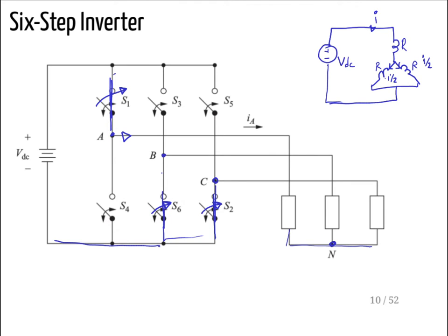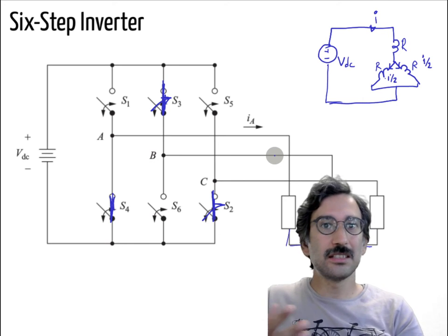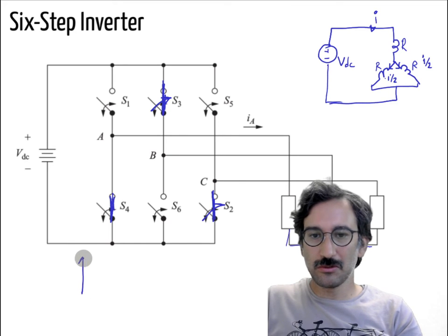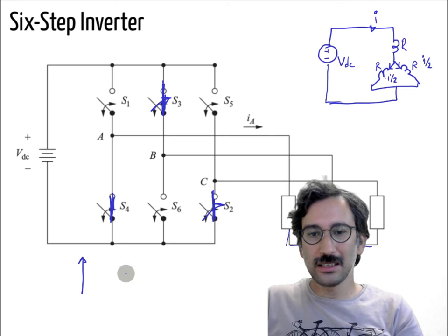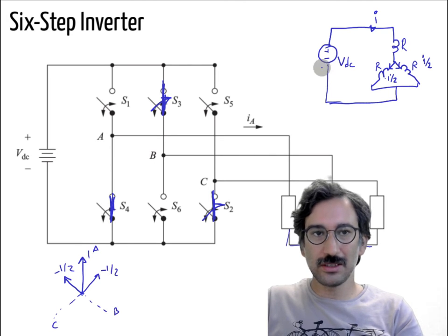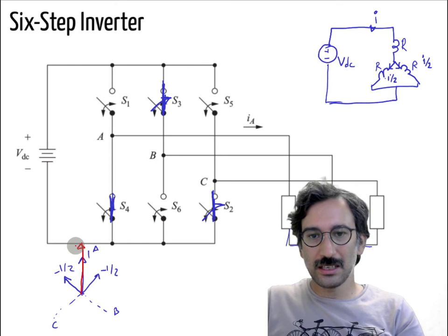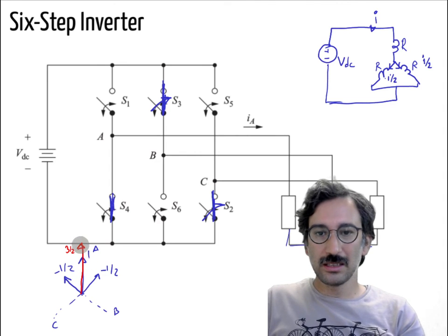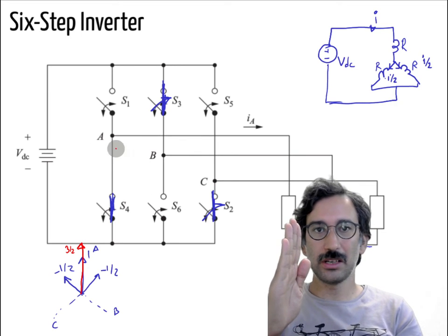We will talk about the sequence as well, but let's say you are turning on that one, for example, then B phase is on, and then the other legs are closed for B and A. If you think about the phasors and MMFs, the motor DQ axis, as you have seen, in this one phase A current is I, and the other currents for phase B and C are minus I over 2 and minus I over 2. Let's say this is A phase, B phase, C phase. So you can generate an MMF of 3 over 2 something. Then your MMF will be aligned with phase A in the first configuration that I showed.